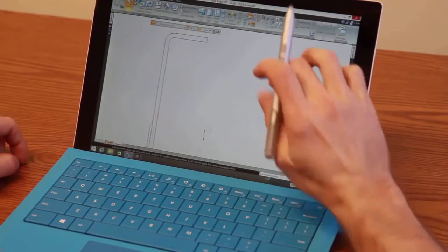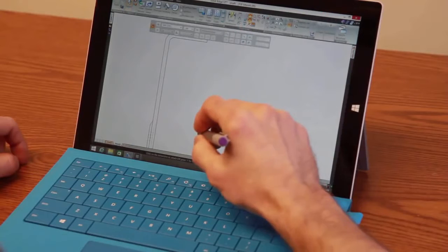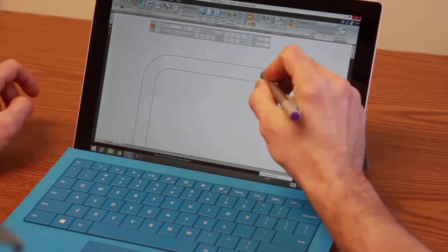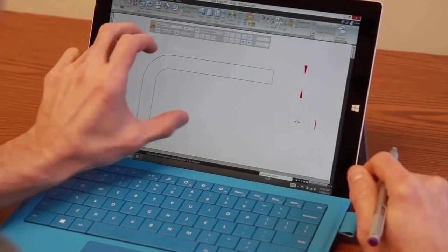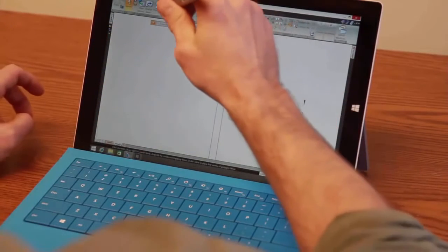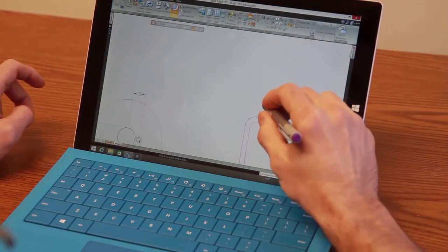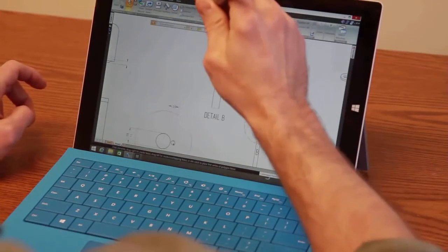Once our views are updated on our draft sheet, we can easily finish our drawings. Now, Solid Edge has informed us that certain dimensions couldn't be reattached upon update, so a quick reattach of our geometry fixes that, and then we can finalize our drawing with a quick detail view of our bin corner. Notice that Solid Edge easily differentiates between stylus clicks and finger zooms, allowing you to use a natural combination of the two.